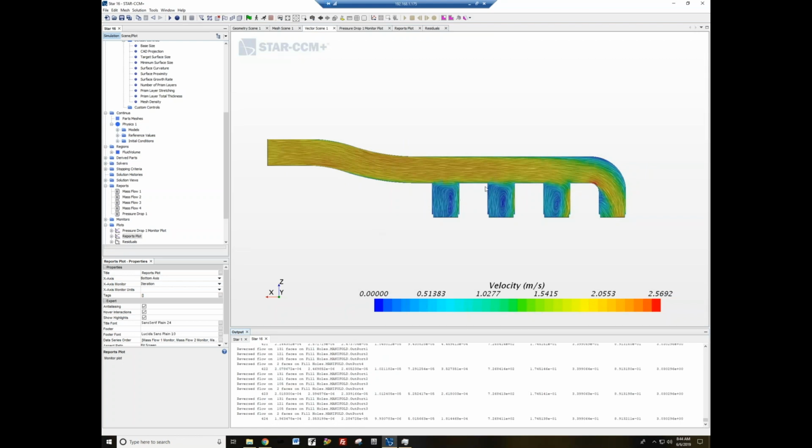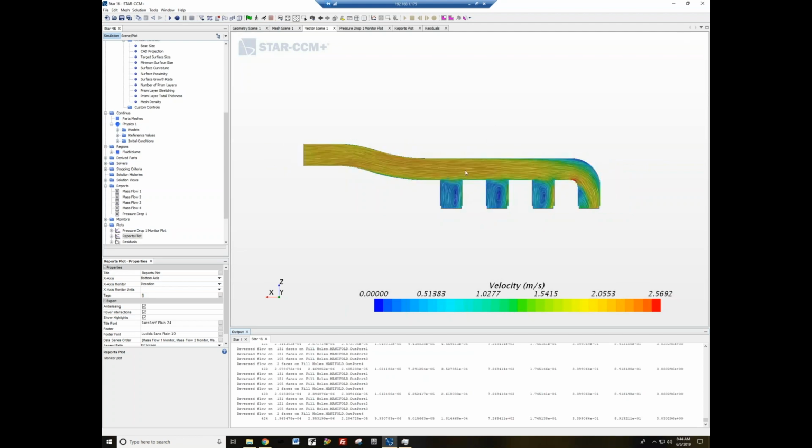We see lots of swirling at the first 3 outlet ports. And this swirling isn't really a good indication when you're having it cut through an actual boundary, because we've put static boundary conditions on each of these 4 ports, forcing a pressure condition at each of these 4 ports. And we see you've got these warning messages popping up saying you're having reverse flow on these outlet port faces.